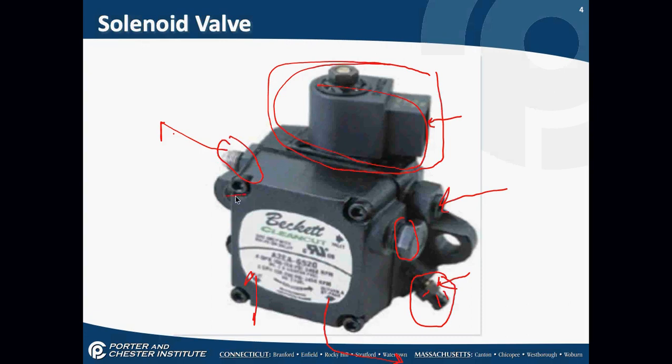Okay, by the way, if I pull out these screws, on most pumps there's a strainer under here that needs to be changed out. If the screws are impossible to pull out, don't attempt to force it, because it means there's no strainer in it, and you'll have a handful of gears if you open these up. So again, just make sure it's a pump that has a strainer in it. If you can't get the screws open, you'd have to use a pair of pliers or something to force them out. Don't open the pump. There's no strainer in it.